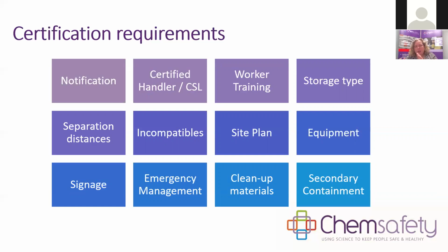containing and dispensing in a controlled manner, and that you've got the documentation associated with that, and similarly that you're using PPE where required. Looking at your signage, your emergency plans, that you have those cleanup or spill equipment, materials and neutralisers, and that you've got your secondary containment. So those are what the certifier is looking at and certifying for your location certificate.